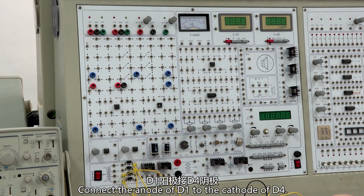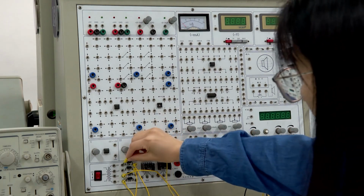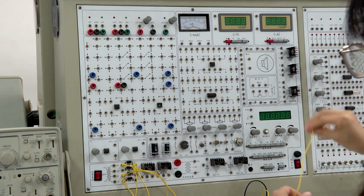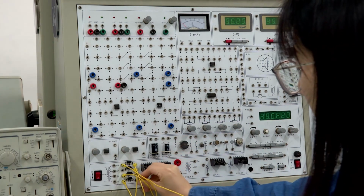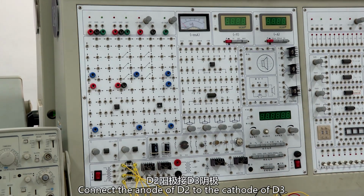Connect the anode of D1 to the cathode of D4. Connect the anode of D2 to the cathode of D3.